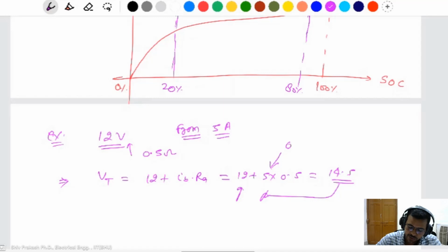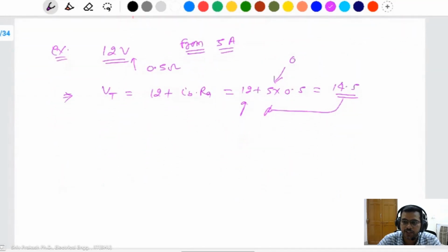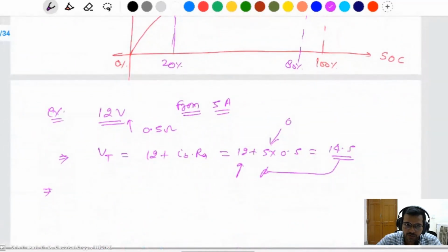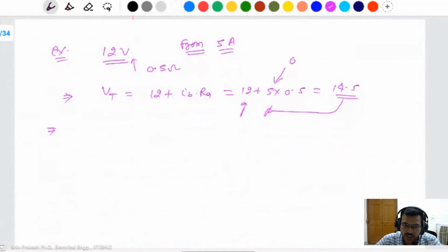In that case, when your battery is charging at 80 to 90%, you should decrease the current to a minimum to charge the battery. It means you charge the battery slowly, not at a higher rate of charge. Then the voltage drop across the internal resistance is very small, and the terminal voltage Vt is approximately the original, real voltage.